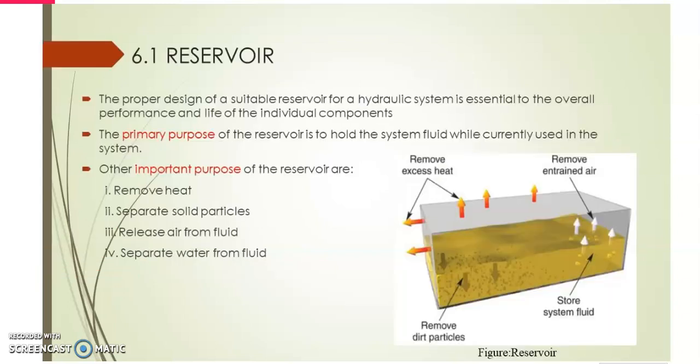Okay, for the reservoir, as you can see here, this figure shows the reservoir. The proper design of a suitable reservoir for the hydraulic system is essential to the overall performance and the life of the individual components. The reservoir serves not only as a storage space for the hydraulic fluid used by the system, but also as the principal location where the fluid is conditioned. So, the primary purpose of the reservoir is to hold the system fluid while it is not currently used in the system. Okay, to hold and to store the fluid.